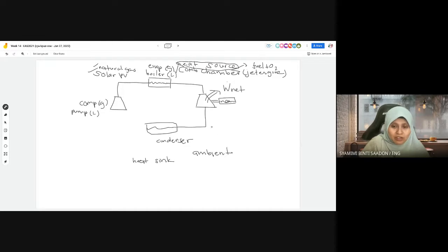So when our working fluid, air or gas, comes out from the turbine, it is at a higher temperature after exiting the turbine. Of course, because it has produced power. So it is at higher pressure and temperature exiting the turbine. In order to cool down and condense, it needs to exchange heat with something, a heat sink, so that the pressure and temperature can come down.